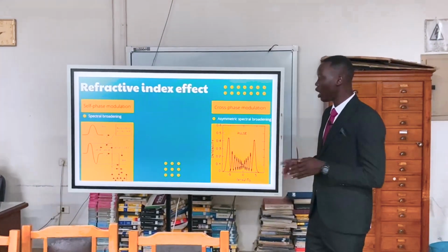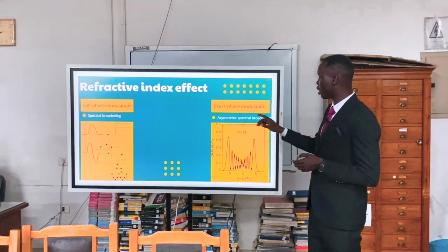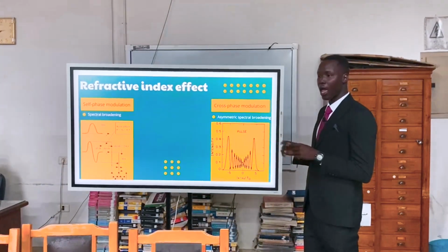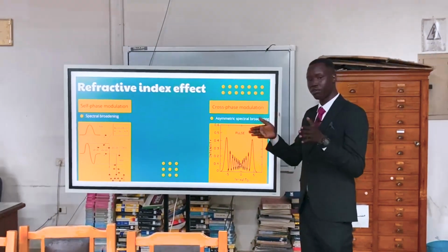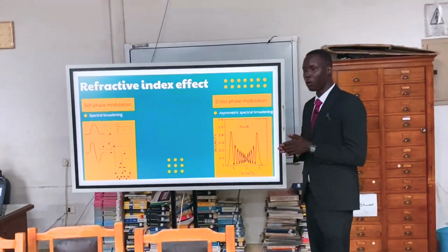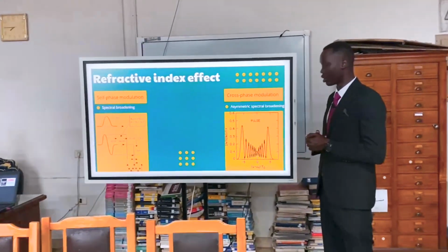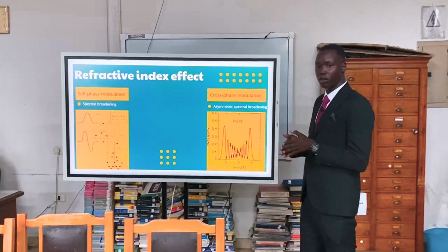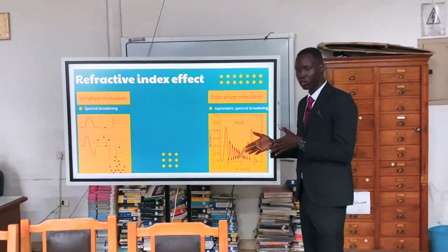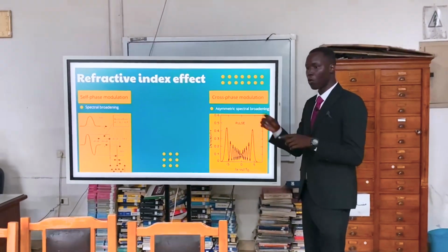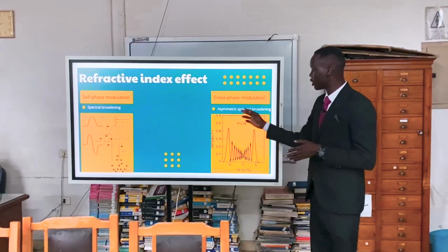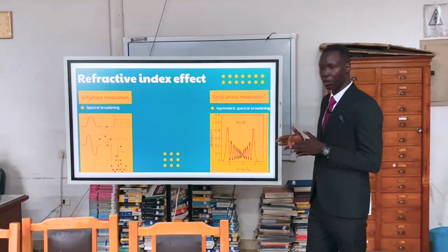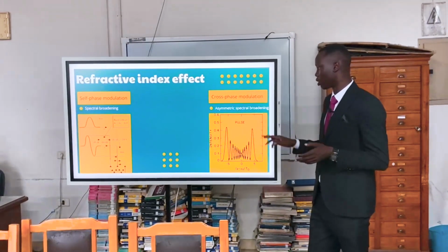A phase shift can also happen as cross phase modulation, where two lights propagate with different frequencies. In this case it can cause signal distortion and also crosstalk, because one of them will have asymmetric spectral broadening, where it is bigger than the other one.